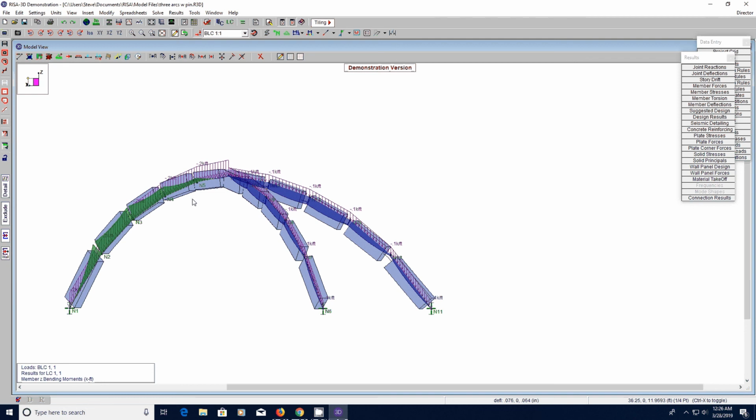It's just a little odd that it's actually pushing up. Again, perfectly balanced, you would get the same moments on this side as you would get on this side, and they would both be the same, whether positive or negative. But here again, positive on this side, negative on this side. So this is something that I'd want to output in terms of the moment diagram.